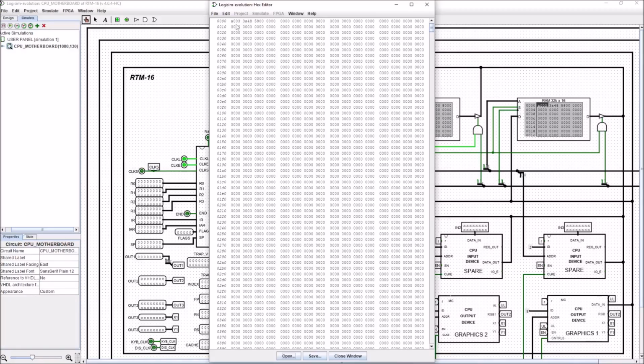So A0 is the code for the C sine instruction. The next 0 isn't getting used, and the final value here, 3, tells us we're putting the answer into register R3. So this is the entire CORDIC sine instruction. Now the next value, 3A48, is the number that we're trying to find the sine of. So in this instance it's 45 degrees. We change it into radians, and then the assembler has converted it into the floating point value, which is 3A48.